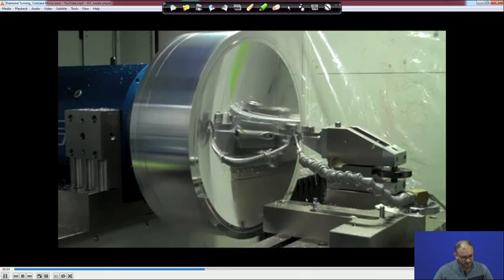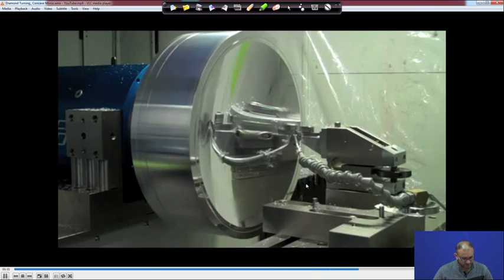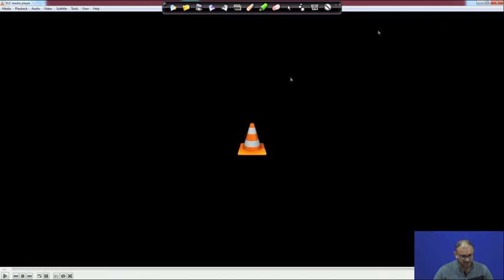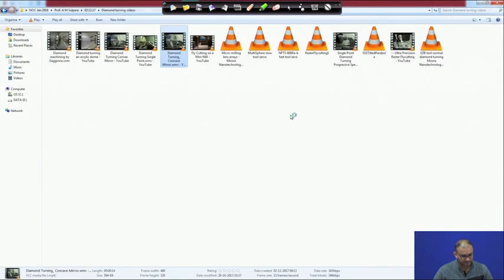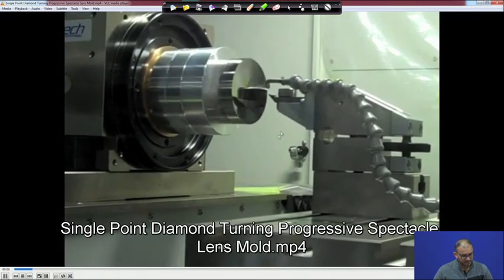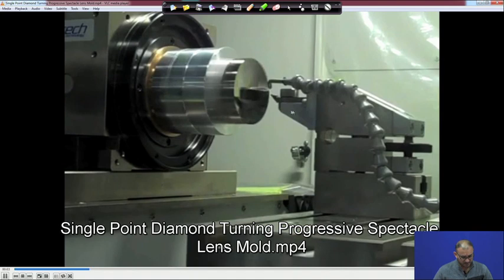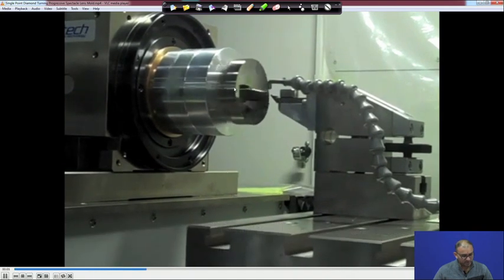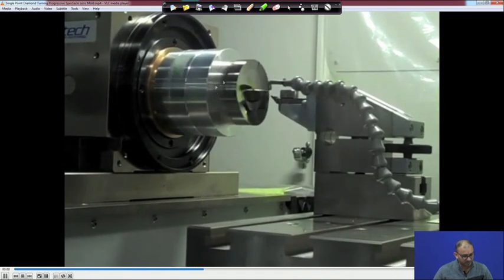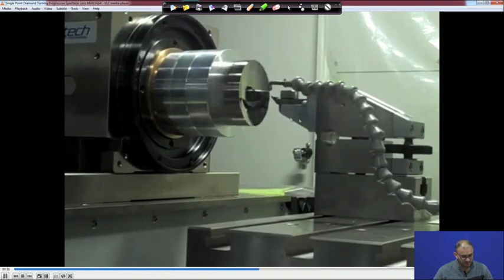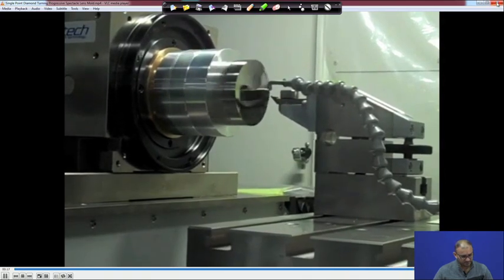Here also the size is very large, and you can see these are the chips coming off. So, you can see that it is almost fine features, so your machining requirement is very less in this case. And this is called the off axis mirror. Now, you can see that you have a synchronization between the rotational motion and the movement in the z axis. So, these are called the servo mechanisms, fast tool servo and the slow tool servo. We will discuss this in detail.